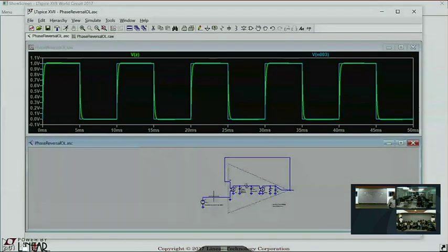Okay, that's the way you transcribe it. And the problem with that is a real circuit can't have exactly 0 dB gain shift unless it has automatic gain control, which means it is not a linear circuit. That's a problem. You're studying stability with linear analysis, but a linear circuit cannot oscillate. That's a problem.